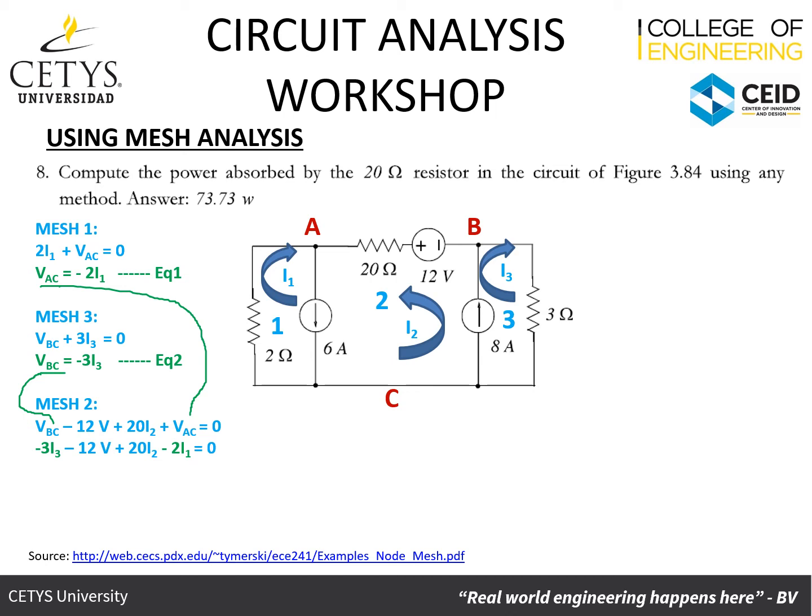And so now we've got an expression that only has the currents, I1, I2, and I3, and we're going to reorganize that one. And so we're going to have an equation that we're going to call equation 3 that's got the three currents: 2I1 minus 20I2 plus 3I3 equals minus 12. We're going to call that equation 3.